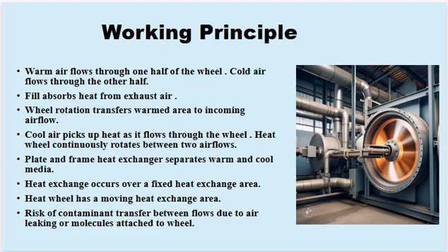Heat absorption: the fill material inside the wheel absorbs heat from the exhaust air as it passes through. Heat transfer: as the wheel rotates, the section of the wheel that has absorbed heat from the exhaust air is transferred to the incoming cold air, warming it. Continuous rotation: the wheel continuously rotates between the two airflows, maintaining the heat transfer process without interruption.